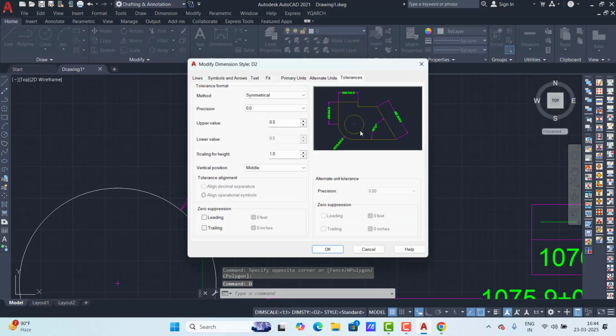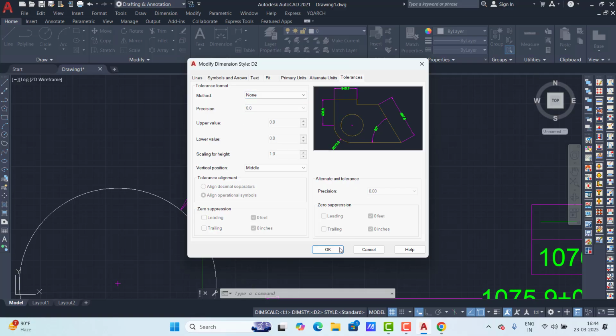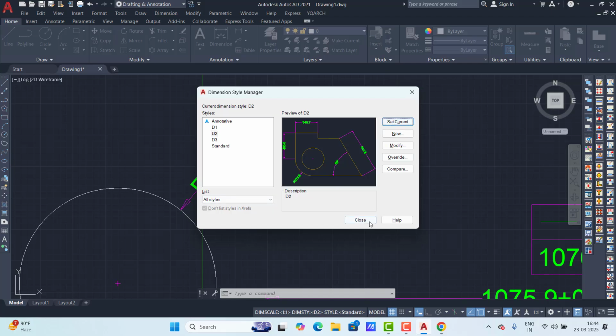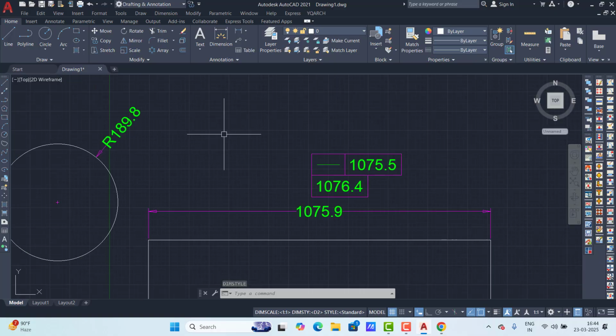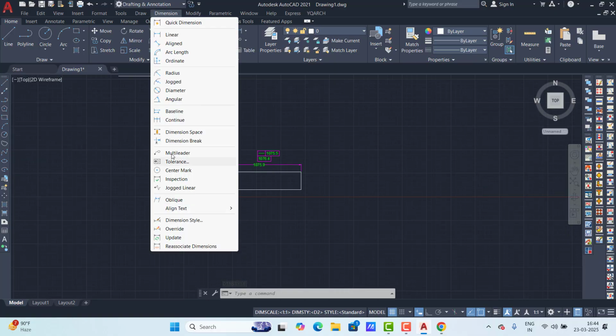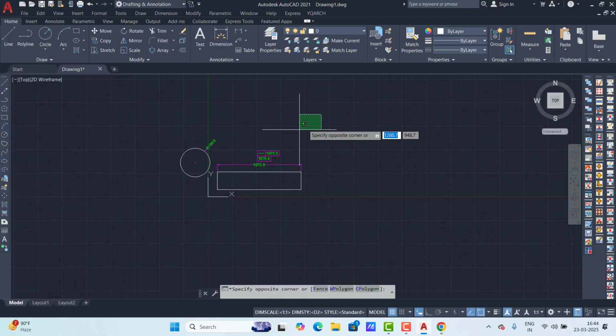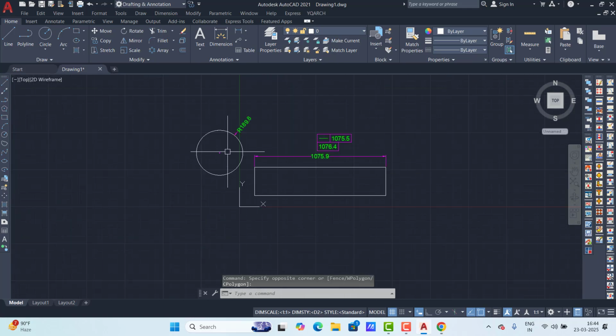Okay. So this symbol means the shaft continues going backside, and the total length is 3517.2. So this shaft is going backside, and this dimension is also going backside. This is the graphical representation. This way you have to present it. That is the dimension type. Okay. Now the next option is oblique and text.